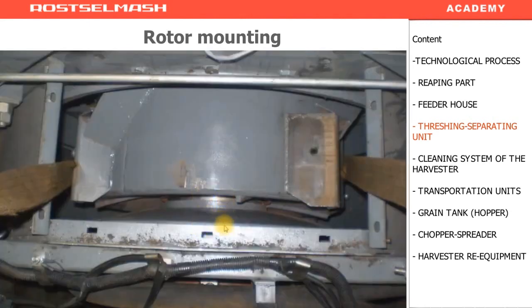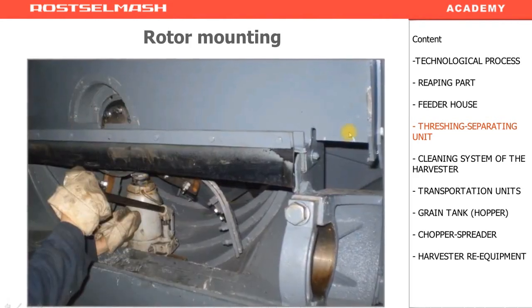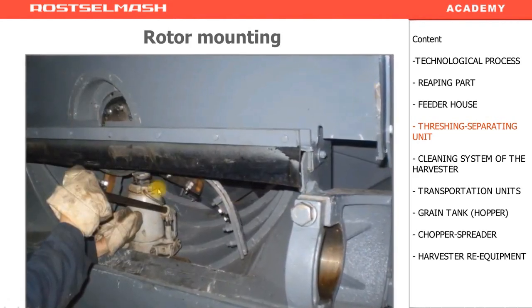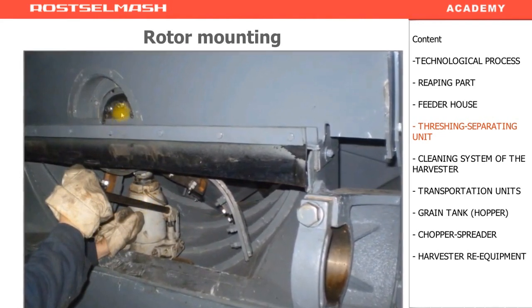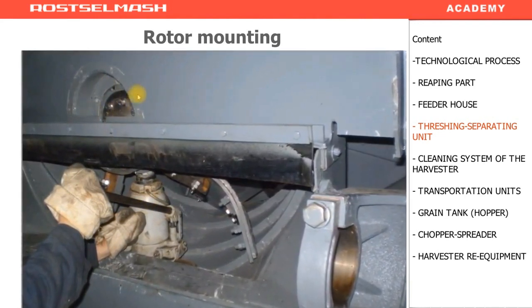After the reduction gear is placed on the rotor, meaning it's fully geared, remove the straps and put the hatch back on, and at the front part of the rotor, you fix it on the support platform, as shown in this picture. So you screw on the support plate, use the jack to lift the rotor, and fix the support bearing.